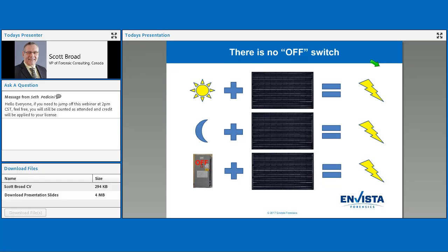It's what they call a diode box, a small box set into a plastic container, and it will overheat in the back of the panel and catch fire. And the problem is when the back of the diode box catches fire, it drips this fire down, and unfortunately this is usually sitting on top of an asphalt bitumen membrane on top of Home Depot, and the asphalt membrane catches fire, and then we've got this thermal event that rapidly grows simply because you've got fire on top of really hard fuel.